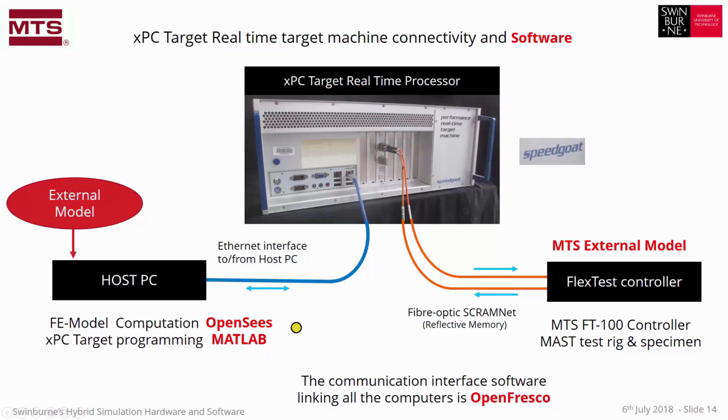The finite element computation that we have running on the host PC is OpenSees. The software running in the XPC target is programmed in MATLAB on the host PC and downloaded from the host PC on the Ethernet. The software running on the FlexTest controller, as we've already referred to, is the MTS external model software.